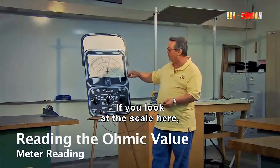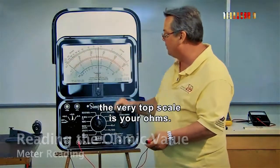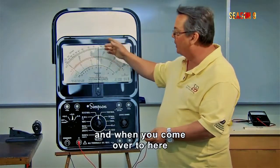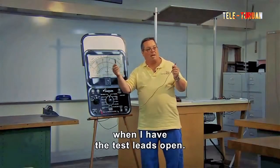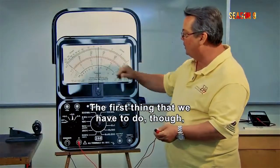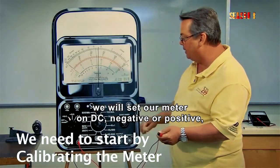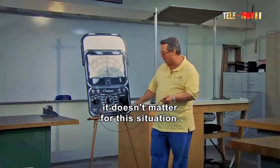Now let's talk about reading the ohmic value. If you look at the scale here, the very top scale is your ohms. 0 ohms here means there's no resistance. And when you come over to here, to infinity ohms, that would be, for example, when I have the test leads open. The first thing we have to do before we can read an ohmic value is set our meter on DC. Negative or positive, it doesn't matter for this situation.